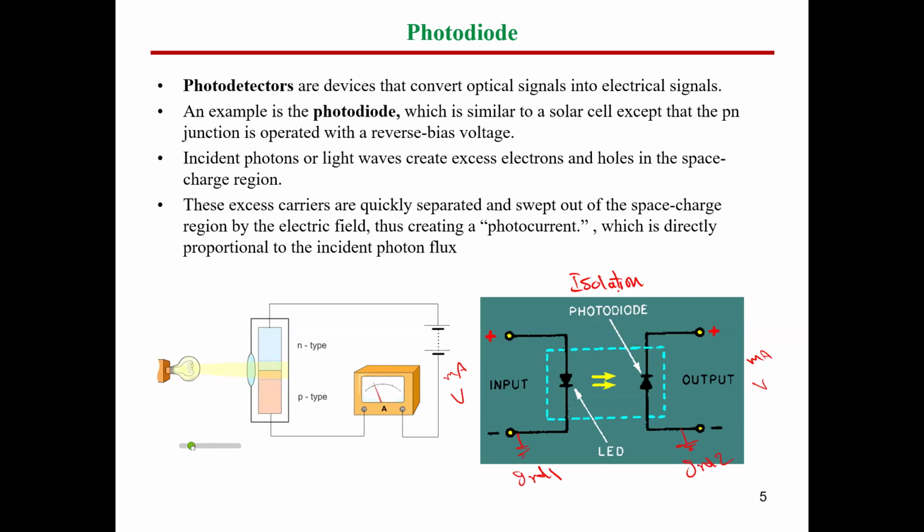We call it, guys, the galvanic isolation. And this isolation can reach relatively high values, like 5 kilovolt, for instance, like 6 kilovolt. So you can find some ICs in industry now with these values.